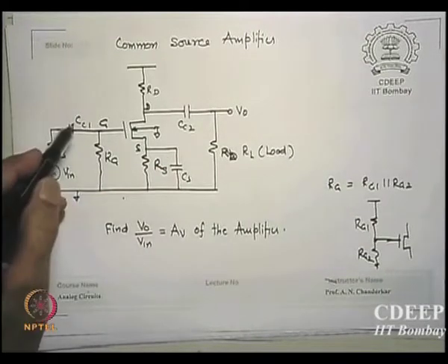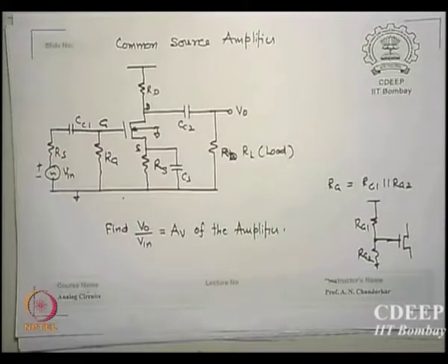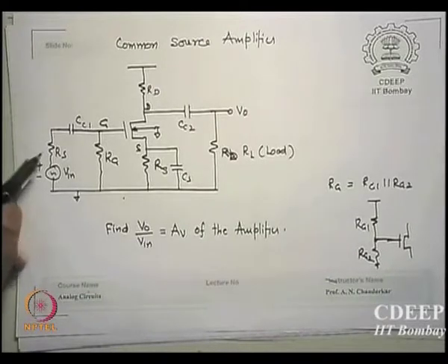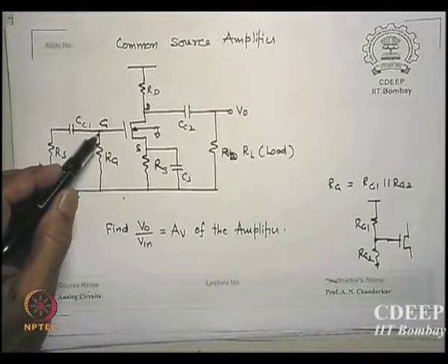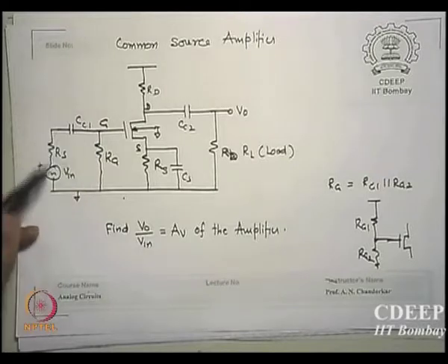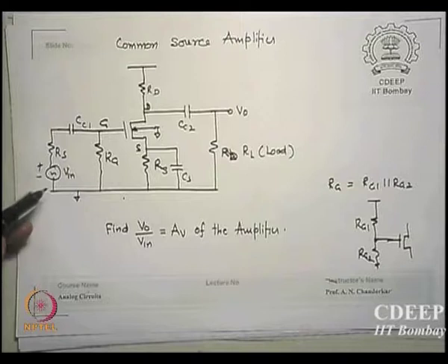But there are two more capacitances I have put here. Their values also should be such that at DC they act like an open circuit. What does that mean? That the DC voltages here, which I am going to apply, should not get connected to the power supply. They should be blocked from the power supply. They may modulate the other side then. Is that correct?